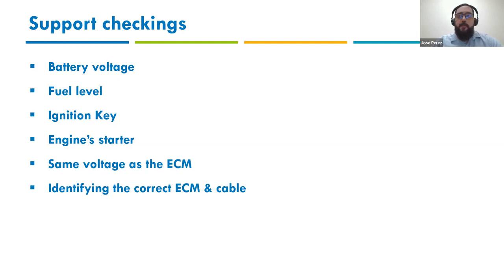You might want to connect to an ECM or a system and you're not able to. What are you going to do? Well, by calling the technical support, with their knowledge, they're able to guide you into identifying the correct ECM you're working on for that system, and guide you into using the proper cable, because as Ignacio said earlier, each ECM, each system has a proprietary cable.